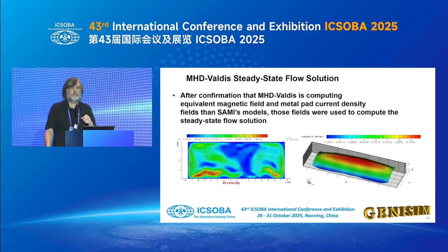They felt confident to go straight to implementation only with the magnetic field and the JY, the improvement of the horizontal current. And so you also get the deformation of the bath metal interface. You also solve the bath flow, but it's required to compute the deformation of the interface. But typically, we are not showing that result unless we are studying alumina dissolution simulation.